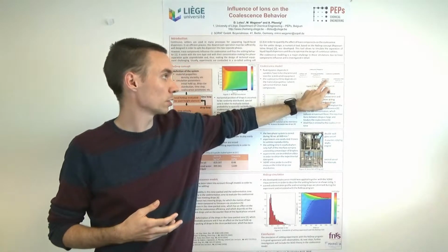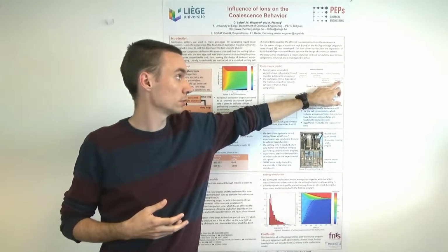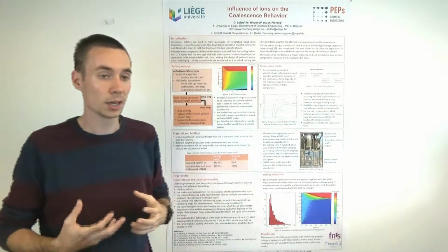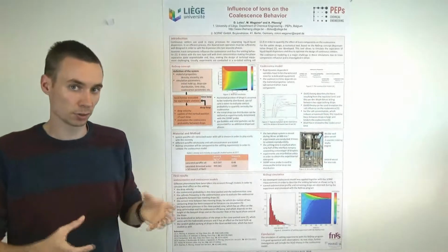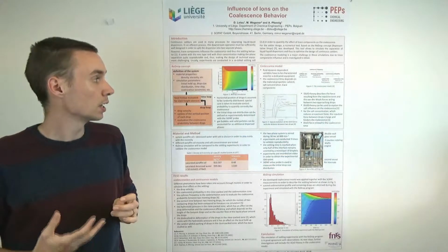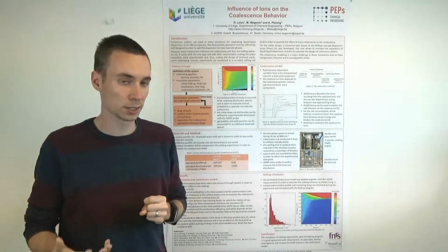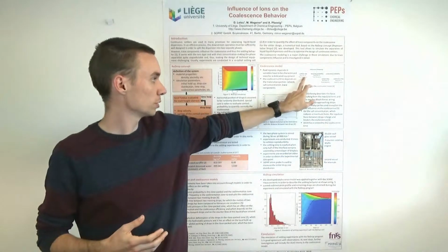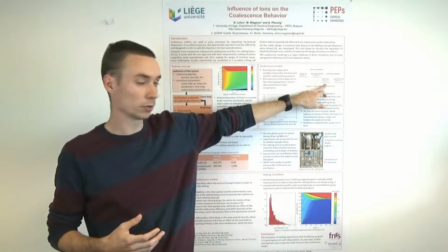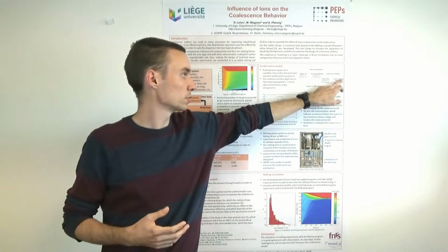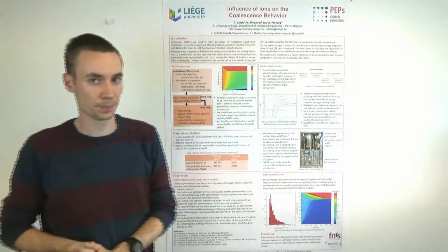These variables depend on the contact time and the coalescence time. The contact time is the time that the drops stay in contact, and the coalescence time is the time that the drops need to coalesce. The first variables depend on the fluid dynamics, and the coalescence time depends on the material system.